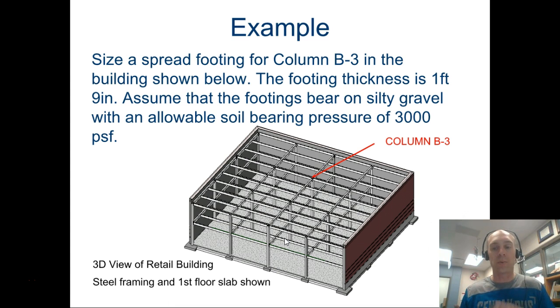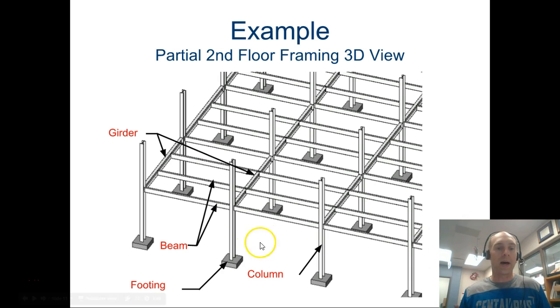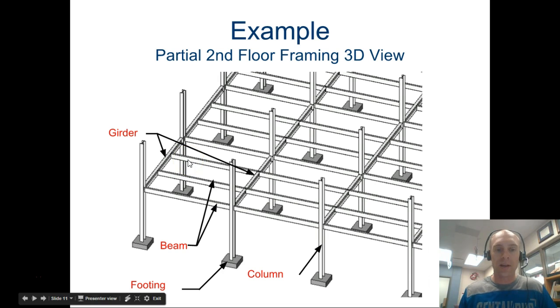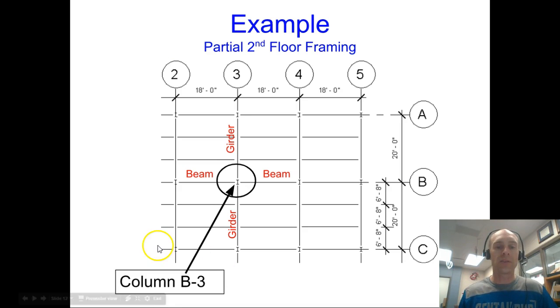So back at this. So we know two things right now. There's just kind of a layout of this. So remember, when you chase loads, the loads from these beams go to the girders, and then from the girders go to the columns, and then all of that goes down into the footing. So we would need to know the loads that are on the beams, then the total on the girders, the total on the columns, to figure out how much that load is going down on the footing. So that's going to be a value that we would have to calculate. We have done a little bit of this to figure out, remember you go halfway to figure out all the loads on the girders.